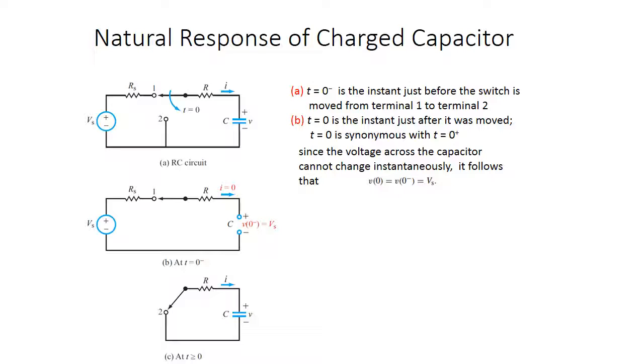So if that voltage source is 9 volts, any point above that capacitor on that top line of picture B is going to be whatever that voltage is. 9-volt source, 9 volts up there. And that's an open circuit right there. There's no current flowing through.